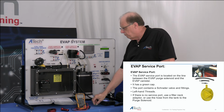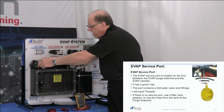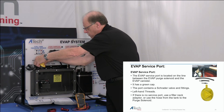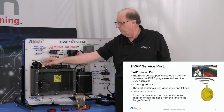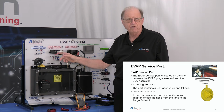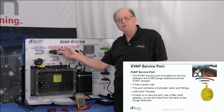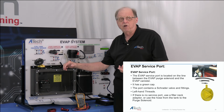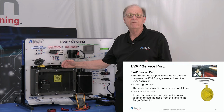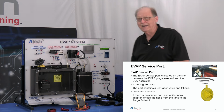If there is no service port, what I would do is take this nice little yellow cap, and there we go, put the cap over there, and I can actually service through here. If I can't service it through there, I'm going to take one of the hoses off the purge solenoid, the one from the tank, and apply smoke or pressure back to check the system for a leak this way. In that process, we're only going to be looking at 1 psi of pressure in the system. Too much pressure is going to damage something. So you're looking at it again, no service port.